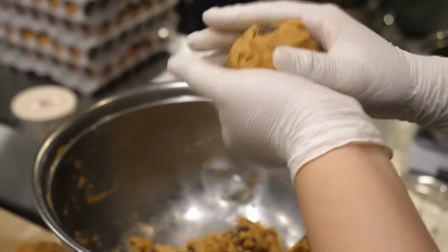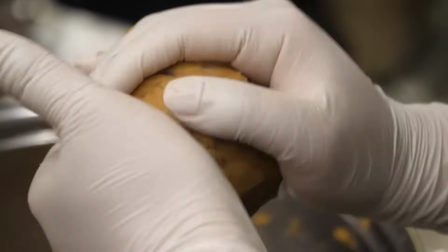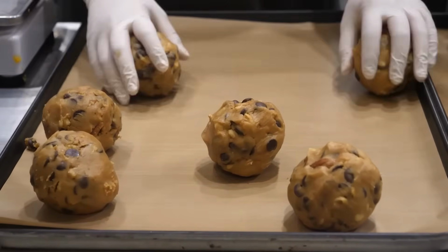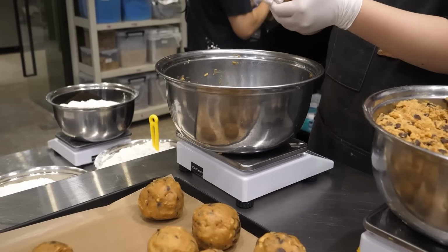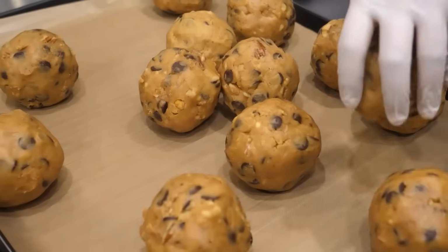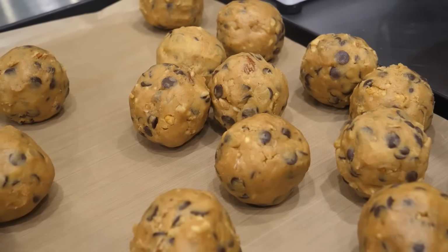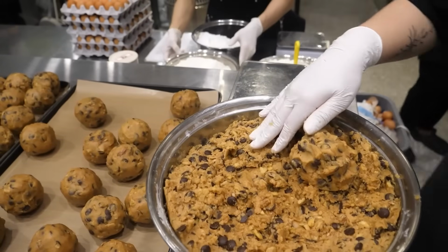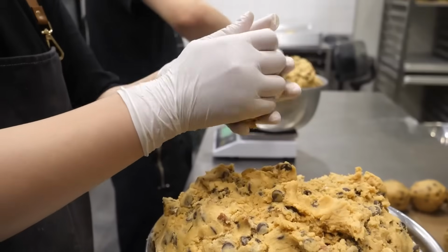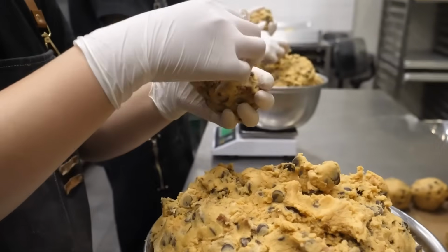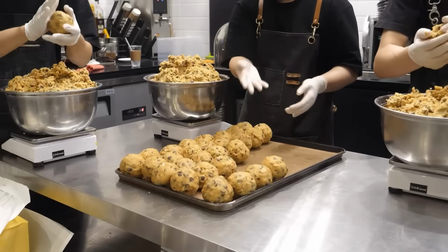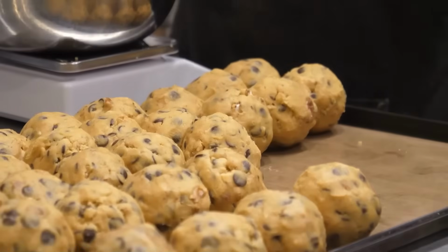Portioning converts bulk dough into individual pieces with defined mass. High volume lines use wire cut or rotary molded or depositor systems. Wire cut systems extrude a dough log through a die, and a moving wire slices portions. Die shape sets cookie diameter. Wire timing sets piece weight.